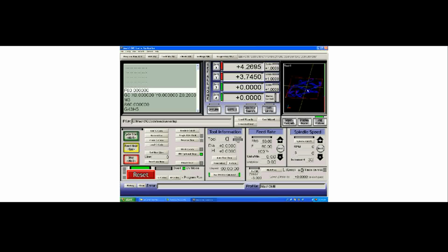Now, whenever you zero DROs, these are the DROs, by the way, digital readouts, the two yellow lines show the X and the Y axes intersecting. So at this moment, my tool is centered somewhere up around this Roadrunner's foot. If I jog my axis, you can see that the drawing moves to show where the tool is currently at when I'm in Jog Follow mode. If I turn off Jog Follow mode, the lines move to show you where you would be. Again, double-clicking will reset the system.